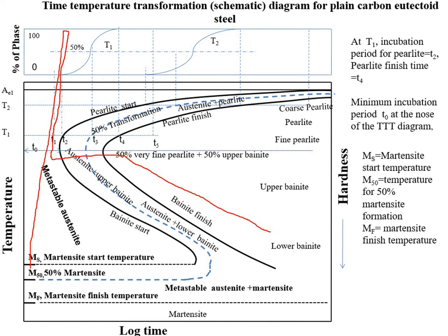So in order to gain bainite, you will be heating it, holding it, and just avoiding this nose region. This is called the nose region, between the pearlitic and the bainitic regions. This is the difference, and this is the nose. So you have to avoid this nose for bainite and also for the martensitic transformations.